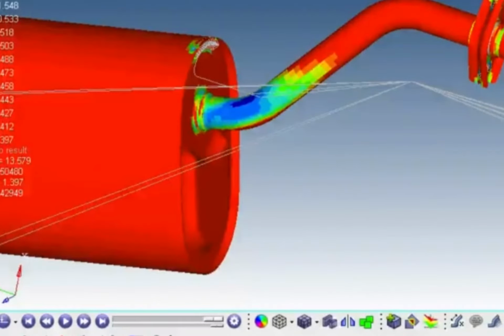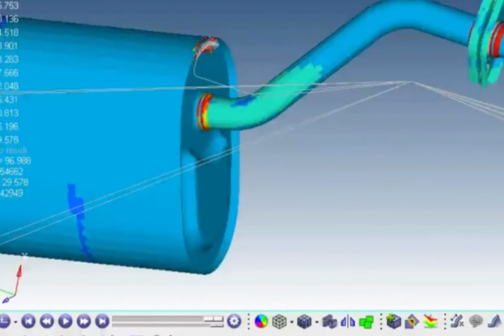We have another parameter here, which is margin of safety. What the margin of safety tells us is how much of the life of the structure has been used up. So if you've got 100%, it means none of the life has been used up. As that number drops, you're using up life, and when you reach 0, you've got no life left. Damage has reached 1. And as we'd expect, the very low margins of safety occur where we were seeing the high damage results earlier. So those are all fringe plots.